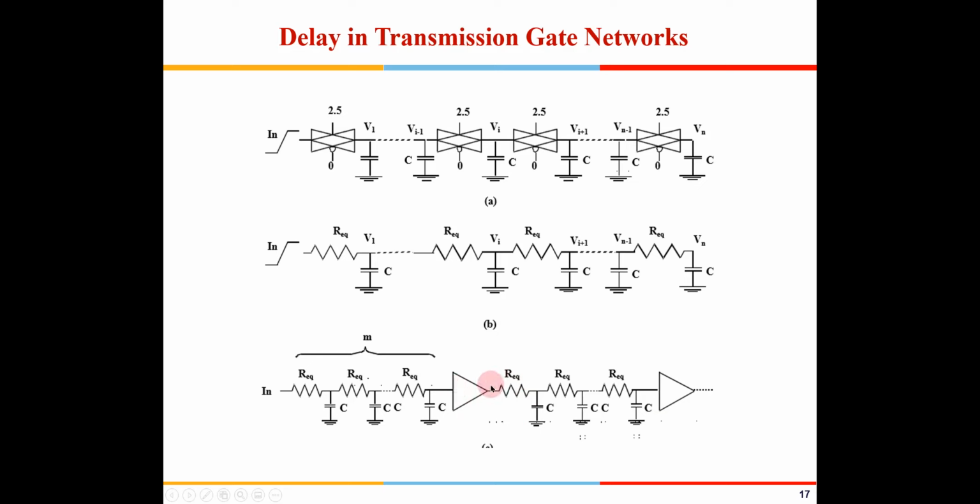That's how the propagation delay can be reduced by inserting these buffers, because they will start the full swing. The input need not swing from VDD to 0. The moment it reaches halfway through, these inverters will start driving the further stages. So that way it will bring down the overall delay. Okay. Is it okay? Shall we move forward?